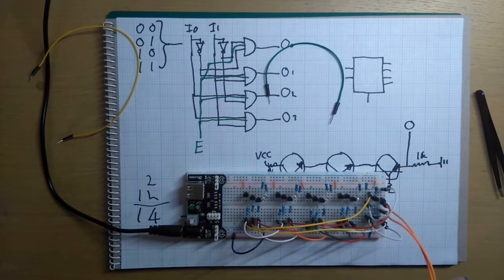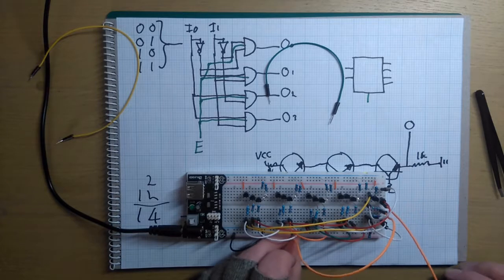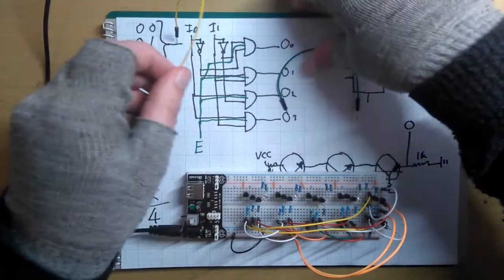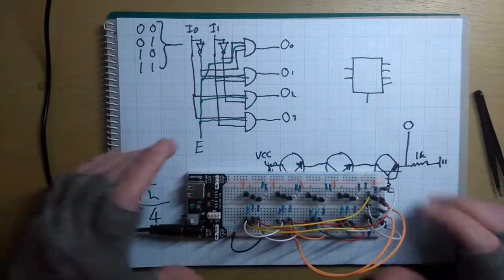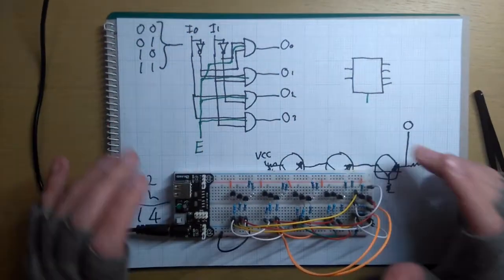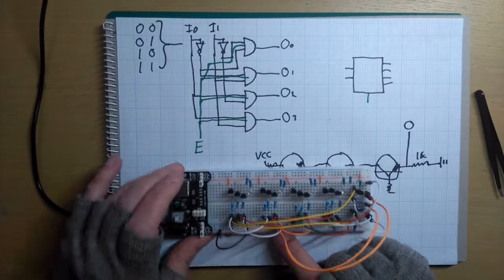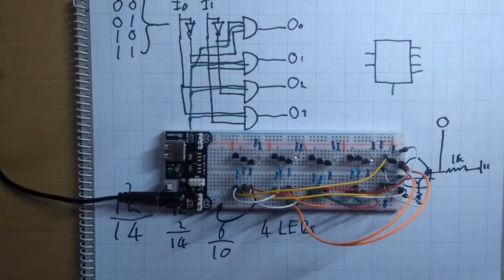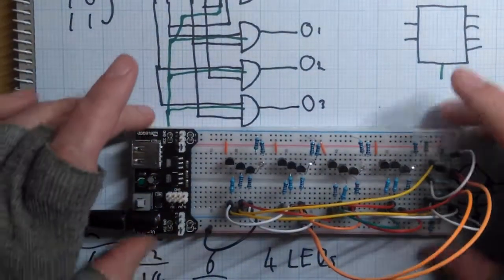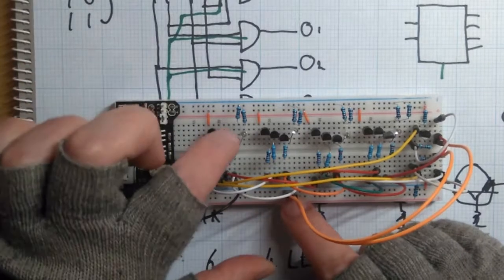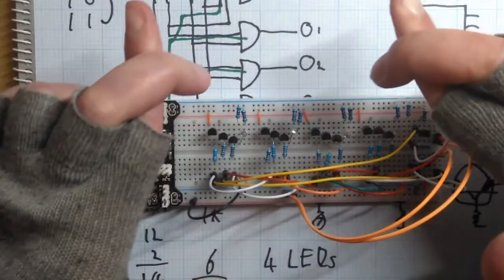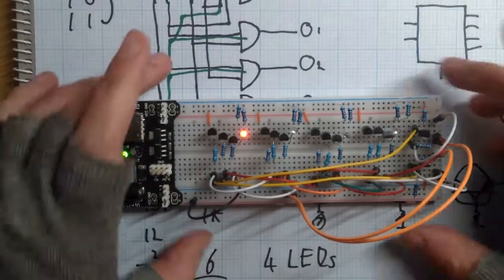Right, okay, that should be everything. So, hold on, let me get this, this is input 0 and this is input 1. Okay, right, we should be done. That's all the bits used. So we've got everything here. So both of these are tied low at the moment. Actually, let me zoom in a bit. Right, both of these are tied low at the moment. So this should be 1. It should be on, off, off, off. Hopefully it works. Hey, it does.